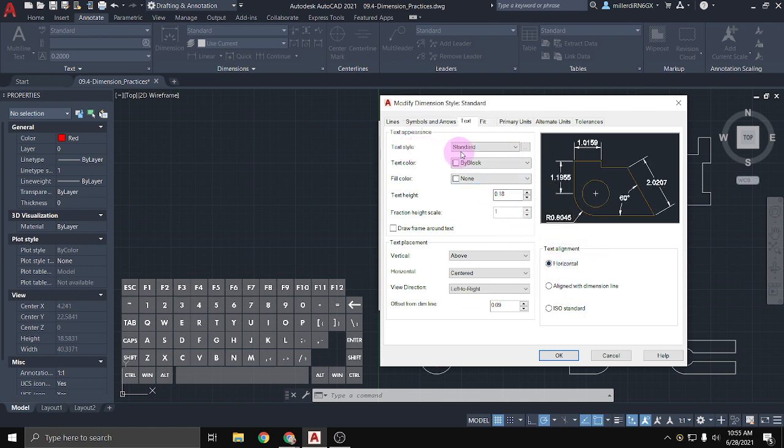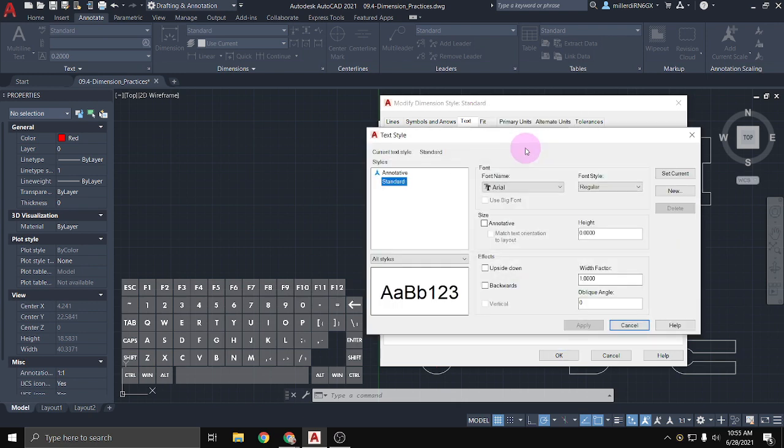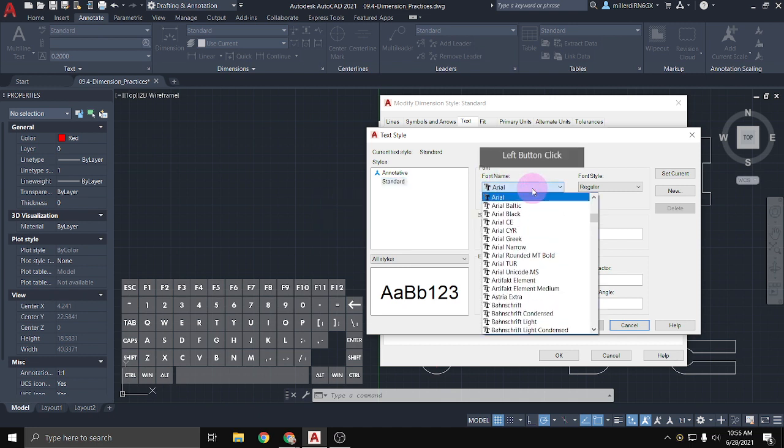We can change our text style too. So in here, I can change my font. So maybe if I wanted it to be more like architectural lettering, I can change the font in here. There's kind of two fonts preloaded on most computers called City Blueprint and Country Blueprint, which we'll go over. That'll look kind of like hand lettering, but typically in drawings we leave it as that Arial font because it's easy to read.